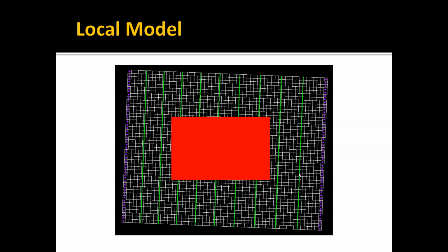And you might say, well, wait a minute. Isn't this still over-constrained? You have a fixed head boundary condition on the upstream side and the downstream side, both of which came from head contours. Yes, but we've already calibrated the regional model, so we have some confidence that our hydraulic conductivity and our recharge are reasonable. Therefore, we can use this kind of locally derived model with more confidence. And so that is the basis of this regional to local model conversion approach.